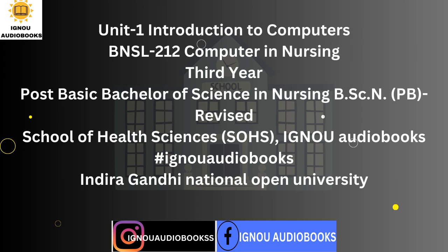Read-only memories can be manufacturer-programmed or user-programmed. While manufacturer-programmed ROMs have data burnt into the circuitry, programmable ROMs let the user load and then store read-only programs. PROM, or programmable ROM, is the name given to such ROM. Information once stored on the ROM or PROM chip cannot be altered.